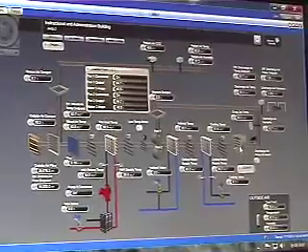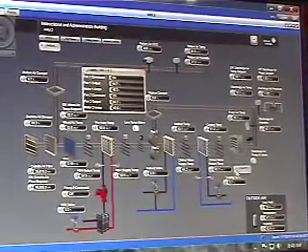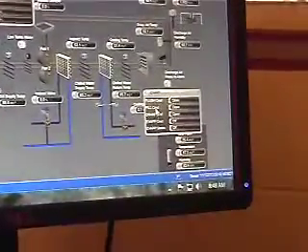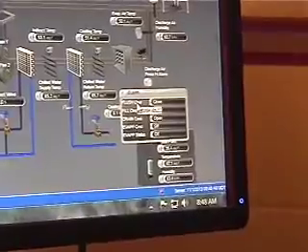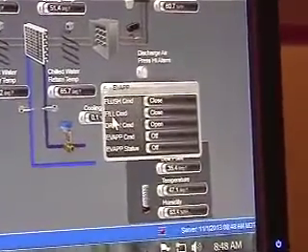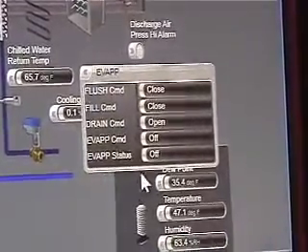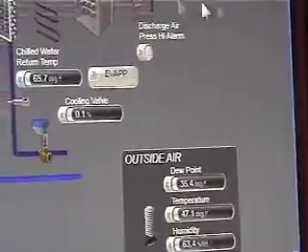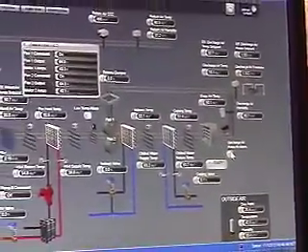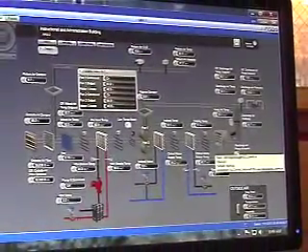Going down here, there's a few more things involved, so it looks like he's created a separate link to it. If you click on this, it'll open up the window for your evap stuff. We kind of mentioned this before, but it's all an automated process. But here you have your flush command, fill command, drain command, and then your evap pump on and off. Go down, discharge air high static alarm here. I believe they're both set at 5 inches, and these are also a manual reset.